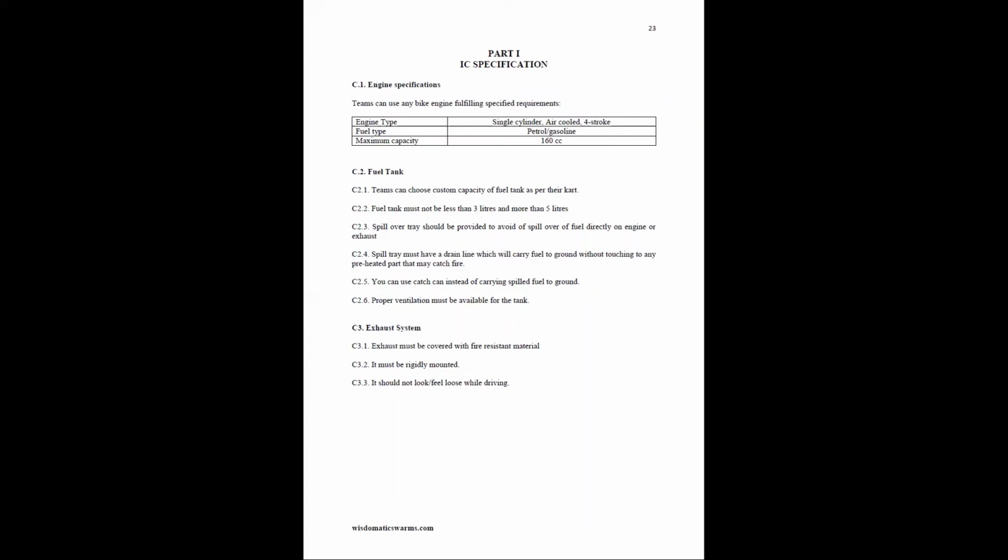Proper ventilation and position of your tank is very important. We would recommend having your fuel tank above your engine head so that with the help of gravity the fuel will flow.